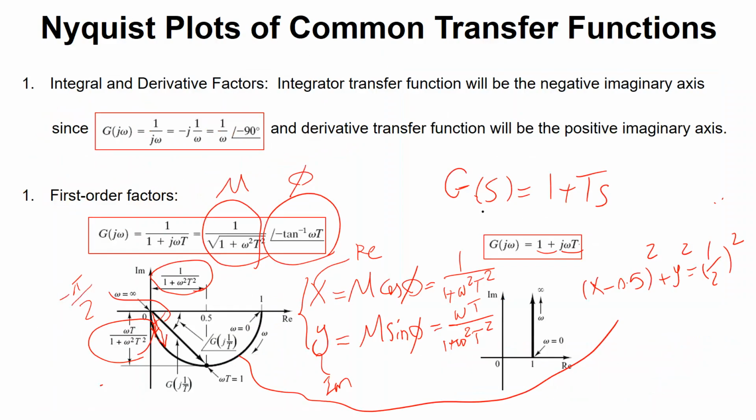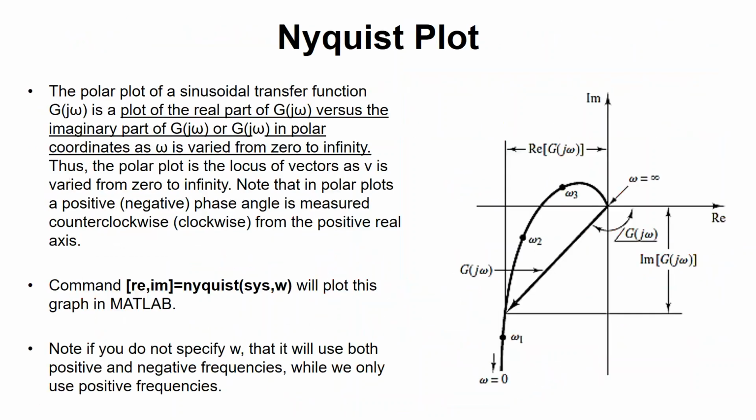If we go back to this picture in general, if any arbitrary point you choose on the Nyquist plot, the distance from origin, right? This distance from the origin to the point of interest, this distance here, is what? This is the magnitude of G of j omega. So where is it that the point on the curve has max distance from the origin?